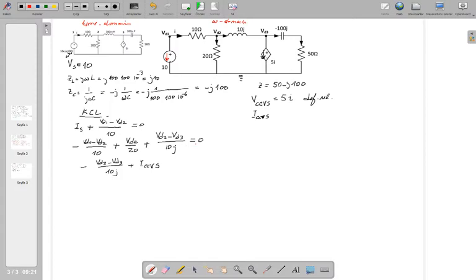This also means that you are introducing a new unknown, because our unknowns in these node voltage methods are the node voltages. So we introduce a new unknown right now. What does this mean? Later on, we've got to write a supplementary equation because of this new unknown variable. Okay, we wrote this current. So what is left is this current.